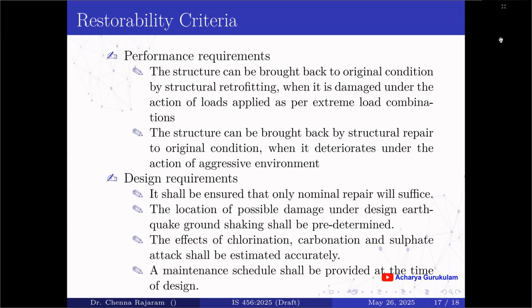Restorability criteria. Performance requirements are that the structure can be brought back to original condition by structural retrofitting when it is damaged under the action of loads applied as per the extreme loading combinations. The structure can be brought back by structural repair to original conditions when it deteriorates under the action of aggressive environment. The design requirements are that it shall be ensured that only nominal repair will be sufficient.